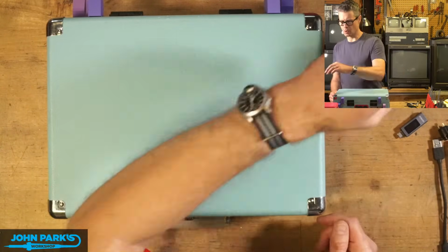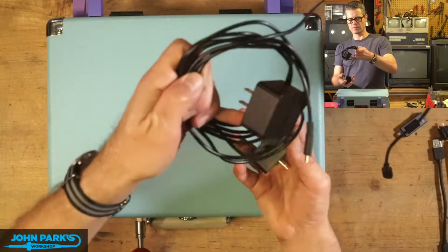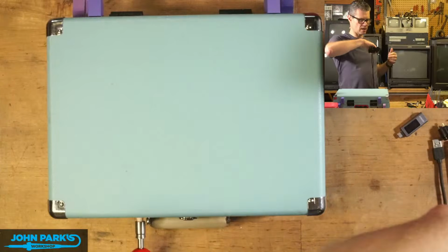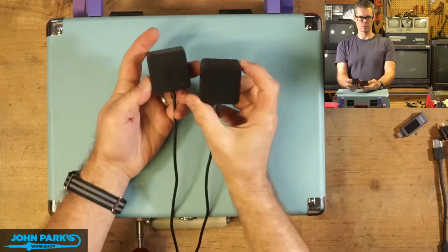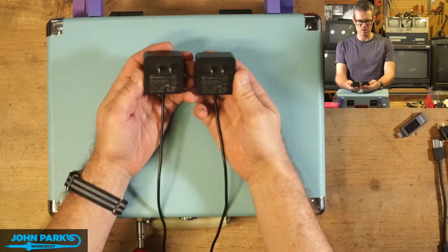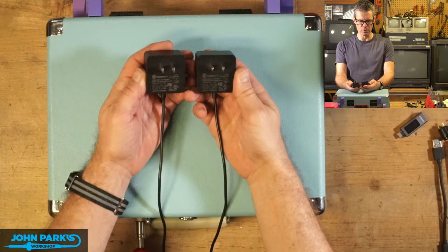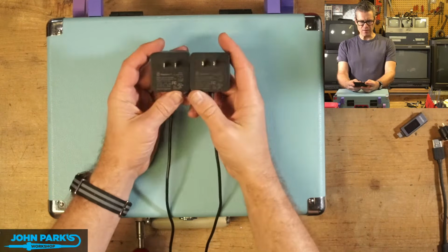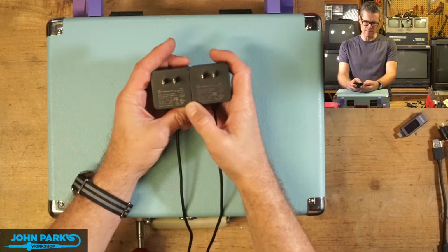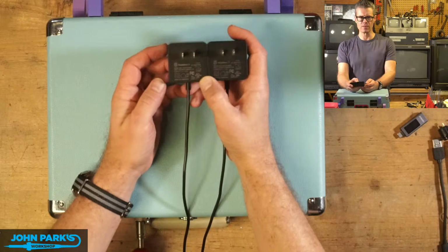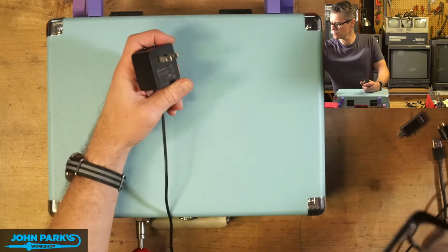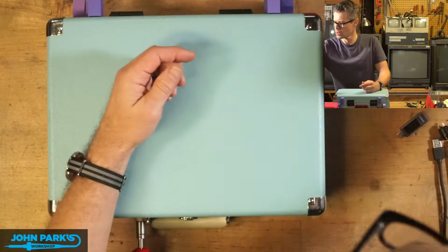And now I think I've gotten it with the proper internal cabling. I've gotten it back to where this will run nicely, I have the monitor and the Raspberry Pi both with their own supply, which is one of these Raspberry Pi supplies. I think these are $7. These are the 5.1 volt, 3 amp. I think the Pi 5 likes that bigger 27 watt better, that goes up to 5 amps, but I'm going to go with these for now just because they're both the same size and they're half the price, and see if after enough testing these work well.